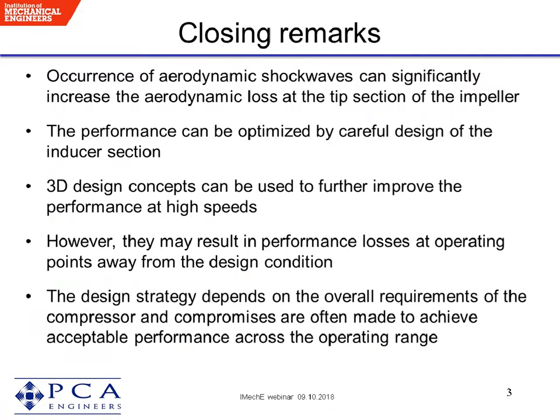Okay, thank you. Yeah. Of course, there's also situations where people use variable inlet guide vanes together with variable diffusers, which gives the widest possible operating range. And if you combine that with variable speed, you can put the map anywhere you want.